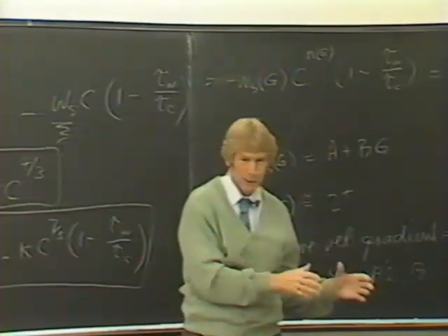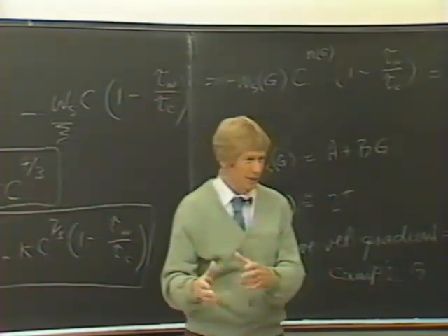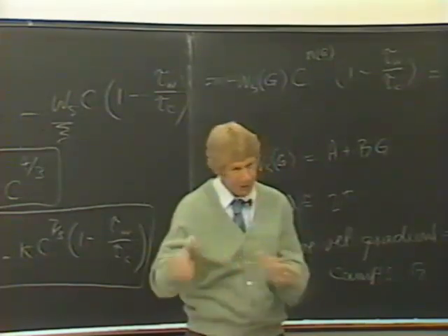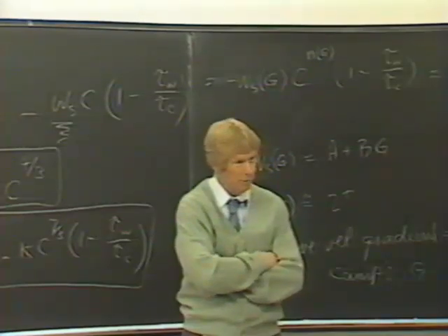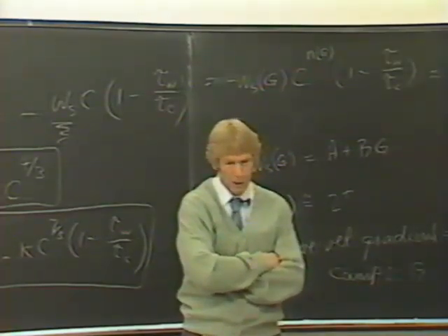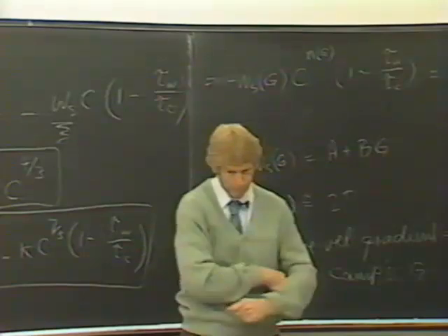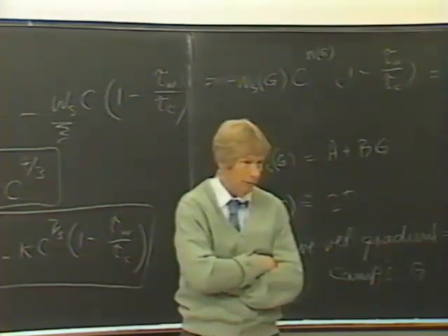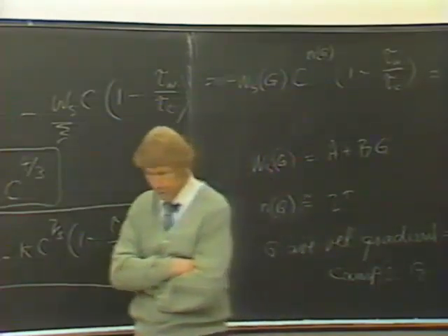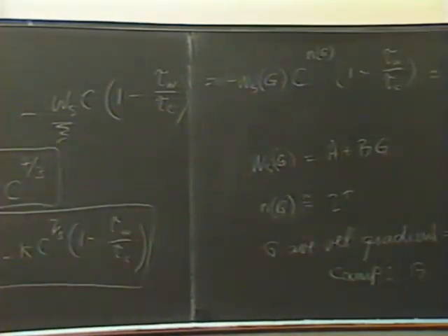In regime 2, if you have a high concentration with hindered settling, you may get a layer on the bed that forms a sharp interface like we saw in the bottle the other day, and hindered settling is taking place down here. But before more than a portion of it can settle on the bed and consolidate, the velocity picks up again, and this is wiped off and carried back up into suspension.